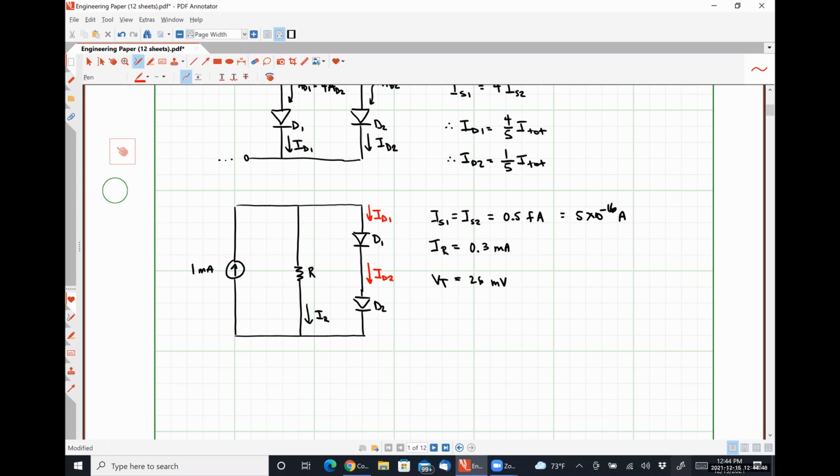Really, the only things that we can't do with a nonlinear circuit are the superposition principle, because that depends on linearity, and the application of Thevenin and Norton equivalent circuits also depend on having some linearity. So KCL, KVL, and by extension, mesh analysis, nodal analysis, all that stuff are fair game. Superposition, we can't do, which you guys never seem to care to do anyway. And then Thevenin and Norton equivalent circuits are also out the window.